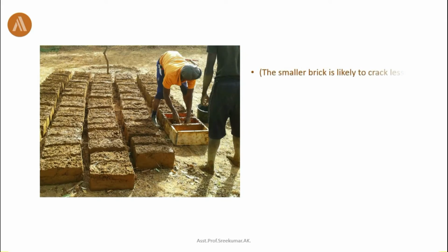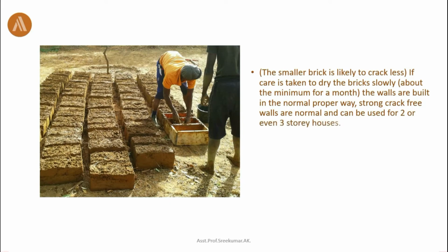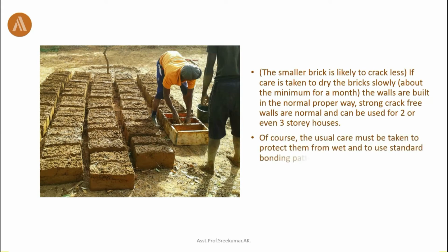If care is taken to dry the bricks slowly, and if the walls are built in the normal proper way, strong crack-free walls are normal and can be used for two or even three-story houses. Of course, care must be taken to protect them from wet and to use standard bonding patterns.